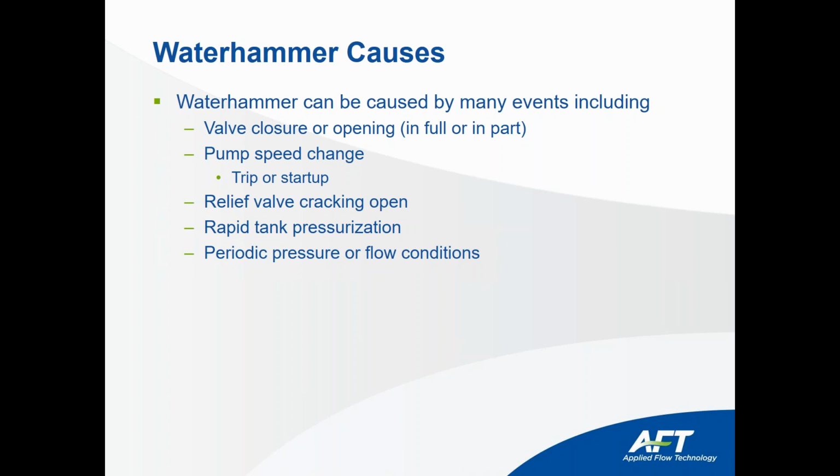Also, a pump speed change can cause it. A trip or start of a pump, a relief valve crack opening, rapid tank pressurization, periodic pressure or flow conditions like when you have PD pumps.